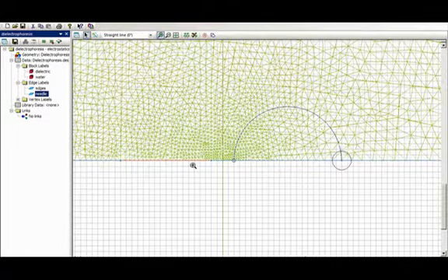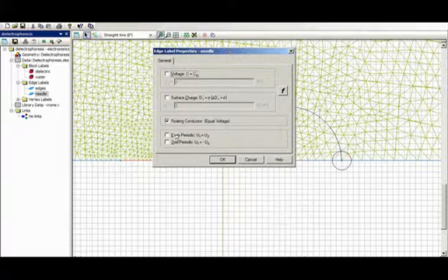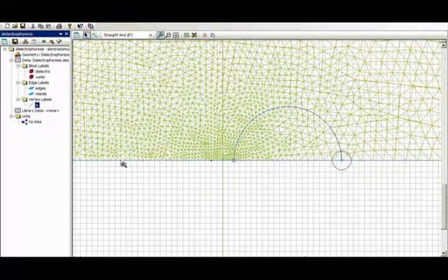It's an electrically charged needle. In order to simulate an object with uniform electric charge, this is a slightly different type of boundary condition. I choose a floating conductor with equal voltage, and I fix a point charge to one end of it. It doesn't matter where I put the point charge on this boundary. This condition will distribute the charge evenly across the needle here.